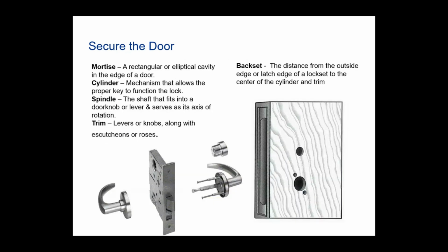How is a mortise lock put together? When putting it into the opening, you take your standard lock set here. Make sure that your cylinder is at the top. The cylinder is a 1 1/4 inch piece of hardware, or 1 1/4 inch cutout. It slides into the door.